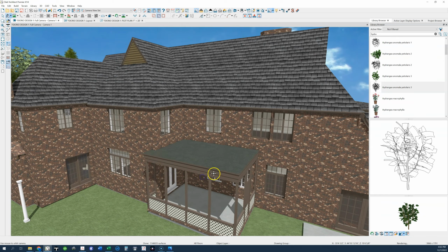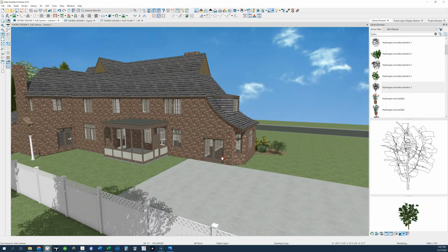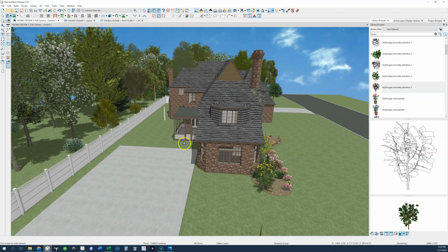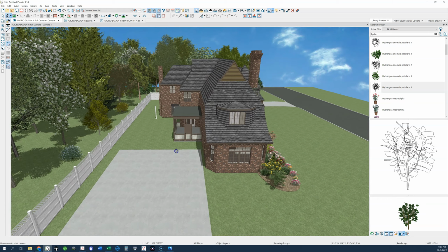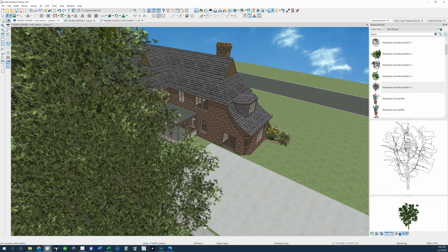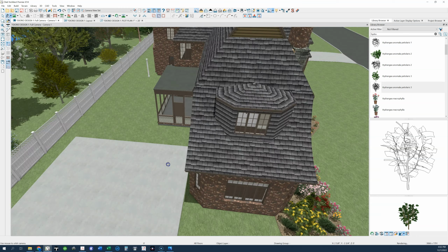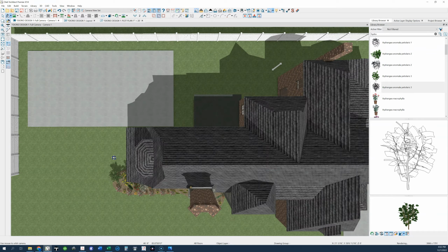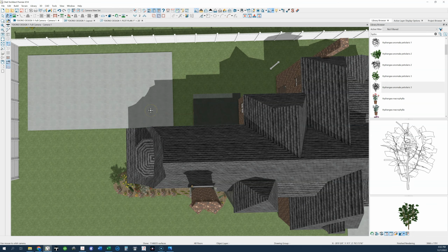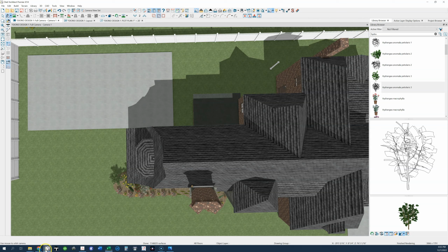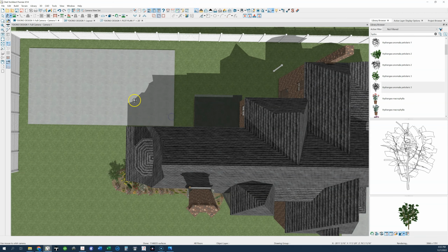This is your existing porch, obviously. I've reviewed your zoning and the setbacks between what your contractor told us, kind of close, not exact. Any accessory structure has to be a minimum of 8 feet away from the main structure. So this here is 8 feet. This is not, just because I wanted to show you what that leaves us to build with a patio on the back. It is also required to have 4 feet from the rear and side property lines, but the 8 feet from the main house is kind of a killer.